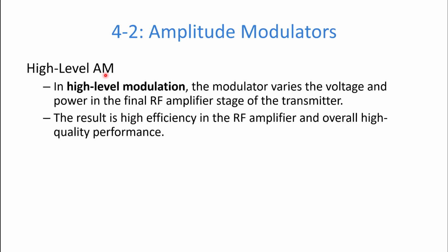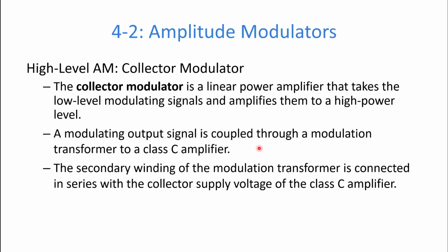Let's talk about high level. In high level, the modulator varies the final RF stage. Sometimes we call that the high power amplifier. It's the very last thing in the transmitter. And this can result in a highly efficient RF amplifier and transmitter, okay?